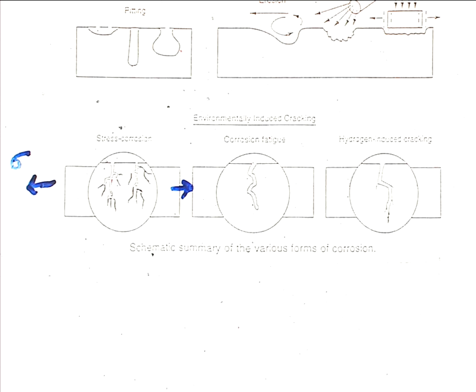Okay, so this one here is an intergranular crack that they're showing, because it's gone round the grain boundaries. So there's a grain in here, and there's another one here, and there's another one there. Yeah, and the crack's gone along the grain boundaries, because the grain boundary is the most reactive part of the microstructure. So, is it transgranular or is it intergranular? Has it gone straight through the grains or around the edges?